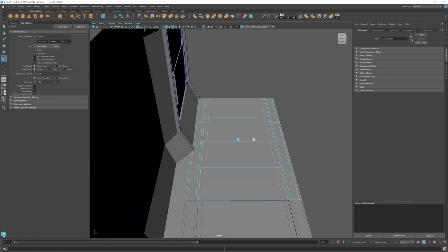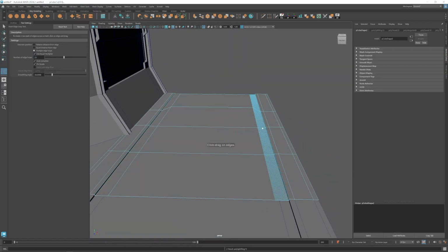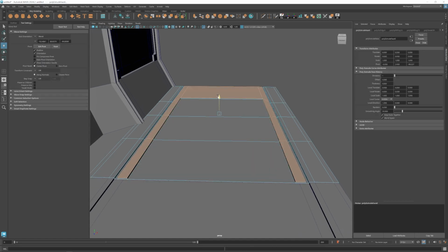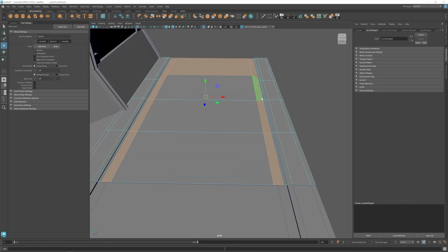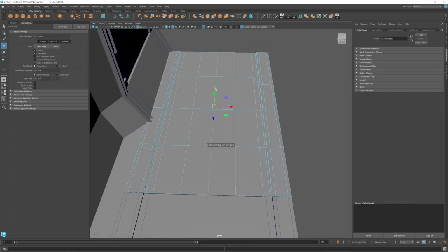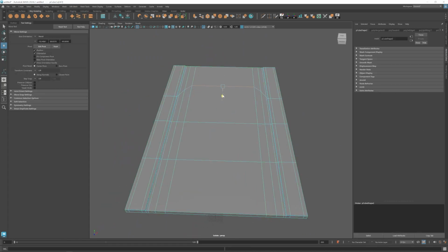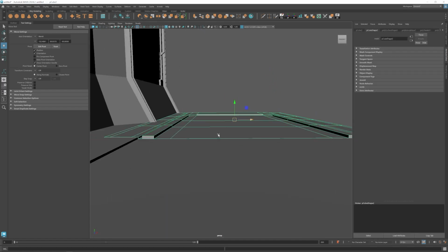When it comes to some of these components, obviously we just simplified them, but if you have more time, I would recommend spending a bit more time making it more mechanically interesting to look at, and you can definitely add a lot more details in certain areas. That's another big thing when it comes to the high poly mesh. Originally, I was planning on adding a lot of elements like booleans and different bolts into the high poly mesh, so we can bake that information over into our normal map and use that lower poly mesh in game.